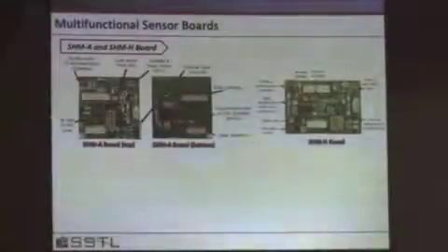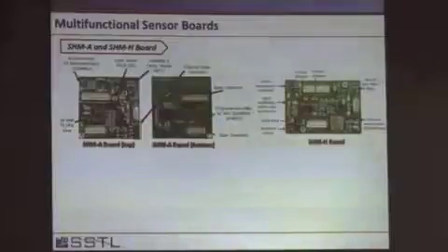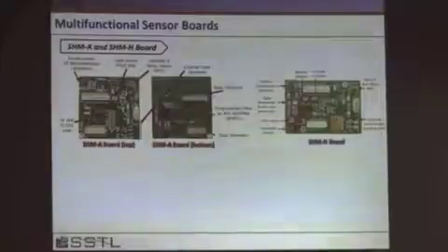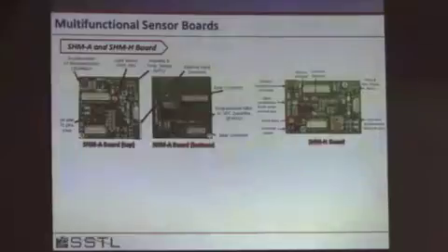So we discarded this sensor board from Intel, and one of my students, Jennifer Rice, designed this sensor board. This sensor board also has a triaxial accelerometer. It has a quick filter chip with a digital signal processor. It allows us to have user-selectable sampling rate and user-selectable anti-aliasing filters. It had a sensitivity of about 0.3 milligis. This was the one that Vincenzo showed yesterday that was used in L'Aquila.